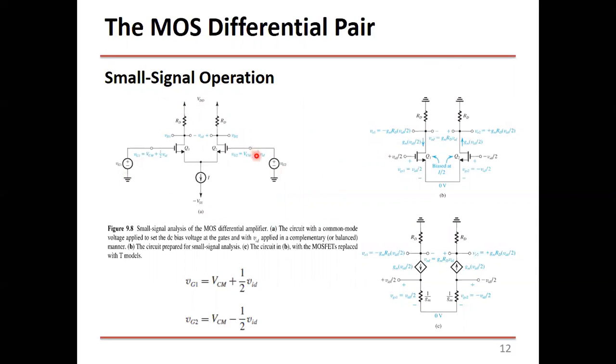Okay, the original circuit. To do the AC analysis, as we mentioned many times, before we do the analysis, we have to do three steps to change the circuit from its original form to the AC equivalent circuit. First, we short circuit or ground all the DC voltage sources. VDD and VSS will be 0. Second, we short circuit any capacitor, any coupling capacitor. We don't have any here.